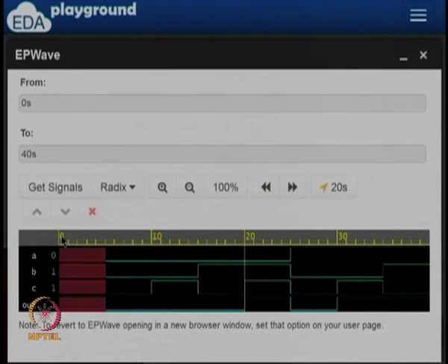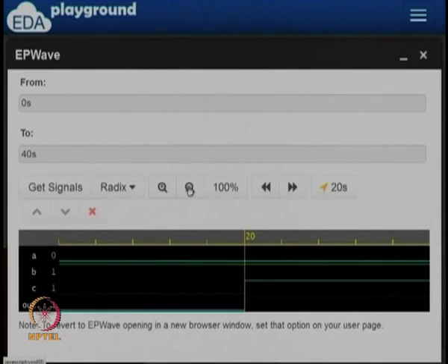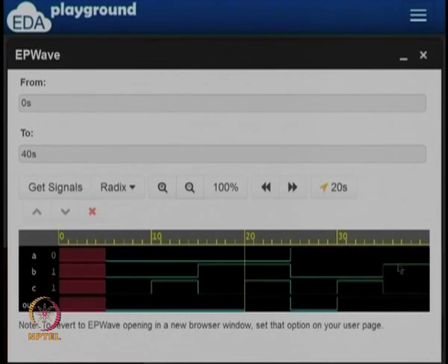You can see that in the waveform viewers, time is on the x axis, and on the y axis you see various signals, and for every signal you can see the time frame. So what are the values of different signals at different points of time, right, and you can zoom in, zoom out and so on. In this case the whole waveform fits here, so there is no more zooming out, we can see all of this design fit into this particular line.